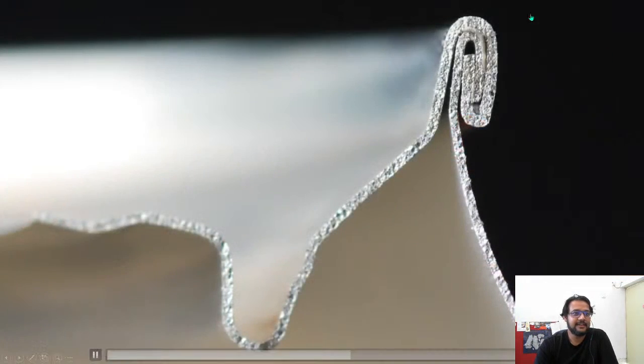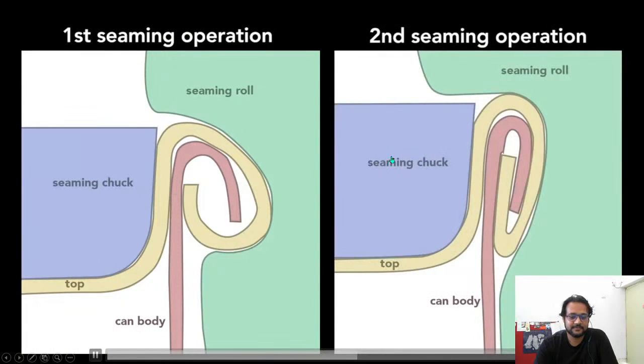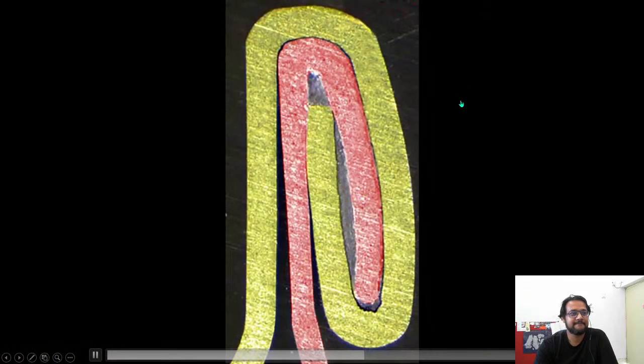Solder contaminated the can's contents. In contrast, today's cans use a hygienic double seam, which can also be made faster. This can is cut in half so you can see the cross-section of the double seam. To create the seam, a machine uses two basic operations. The first curls the end of the can cover around the flange of the can body. The second operation presses the folds of the metal together to form an airtight seal. While the operations themselves are simple, they require high precision. Parts misaligned by a small fraction of a millimeter cause the seam to fail. In addition to the clamping of the end and can body, a sealing compound ensures that no gas escapes through the double seam.